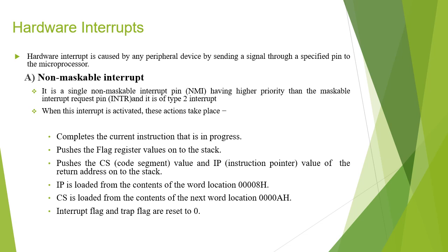Also, it will push the current CS and IP values on the stack. So whatever is required in order to resume its operation once that interrupt is completed is stored in the stack. Now the IP will be loaded from the contents of the word location 0008H.